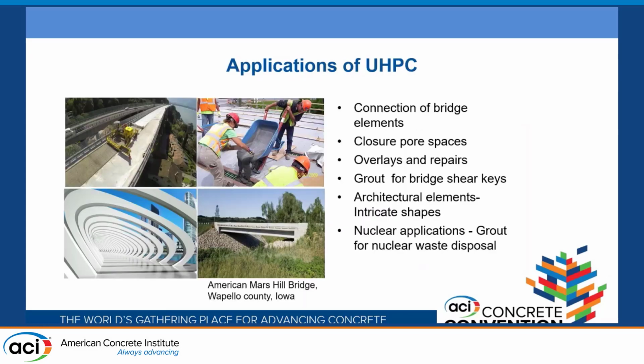Because of its exceptional properties, field cast UHPC finds its application in various construction projects such as connection of prefabricated bridge elements, closure of pocket spaces in pile caps, overlays and repairs for bridge decks, and as grouts for bridge shear keys.